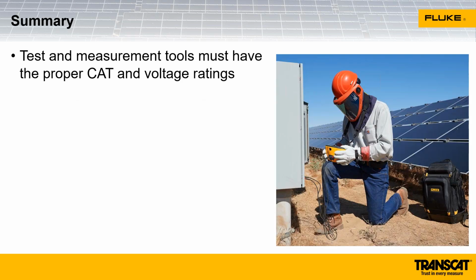So to wrap things up here, all of our test tools are going to have a category and a voltage rating. We need to make sure that those are appropriate for the environment that we're working in and the voltage rating of the system that we're working on.